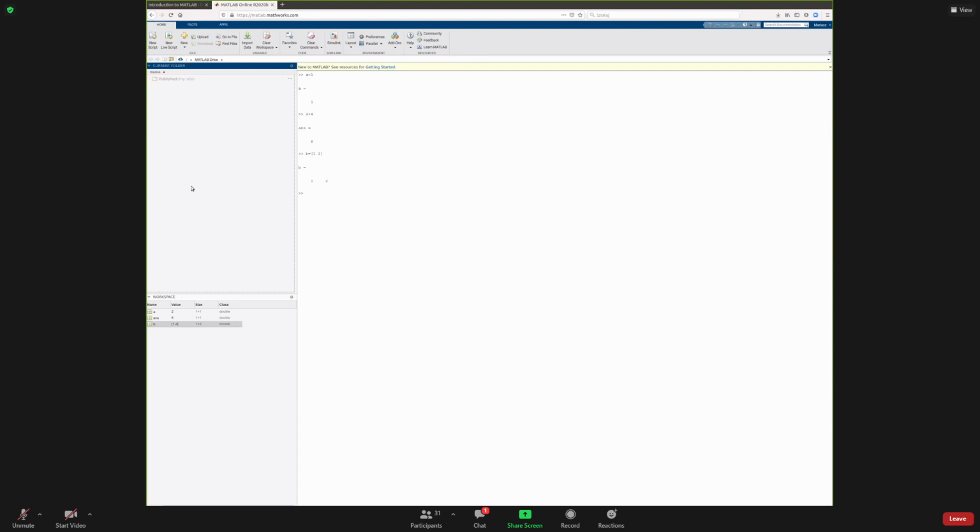You can navigate over your file structures. But the thing you need to remember is that MATLAB assumes that when you try to run any script, it looks for this script first in your local folder, I mean the current folder, right? When you change the folder, MATLAB will probably have a problem finding your script. So be sure that you are in the right folder before you start